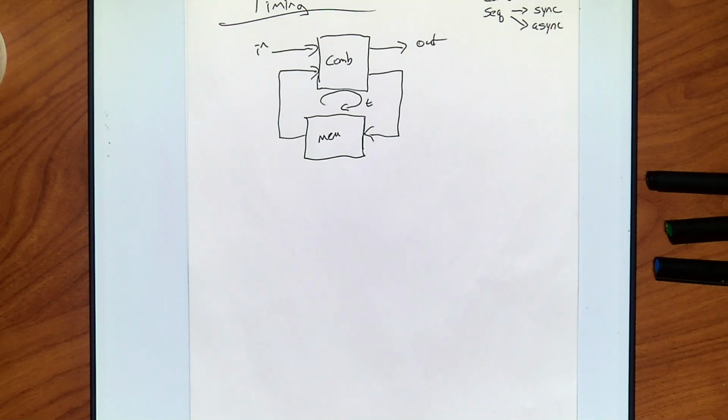If we have an always block, or in SystemVerilog, always_comb, always_ff for flip-flops, or always_latch, things of this sort, you're going to have an at sign and a sensitivity list. That's the event list. There's only one function that can handle it, what you write inside that block.